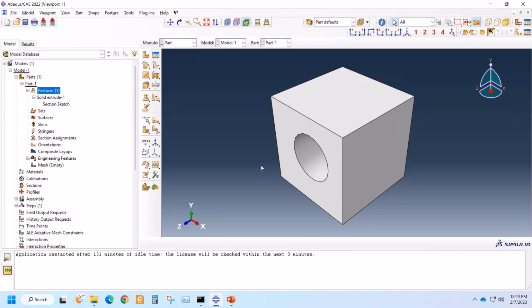But are there other methods? Yes. Sometimes you may have to use an orphan mesh. Generally, we use a geometry or import a geometry, but sometimes we don't have a geometry. We have to start with an orphan mesh. That is just a mesh, not a geometry. So we can create a geometry from the orphan mesh for our use. Also, if our existing geometry, let's say we have imported from somewhere else, probably from some other software, is faulty as per ABAQUS definition, there are repair tools.